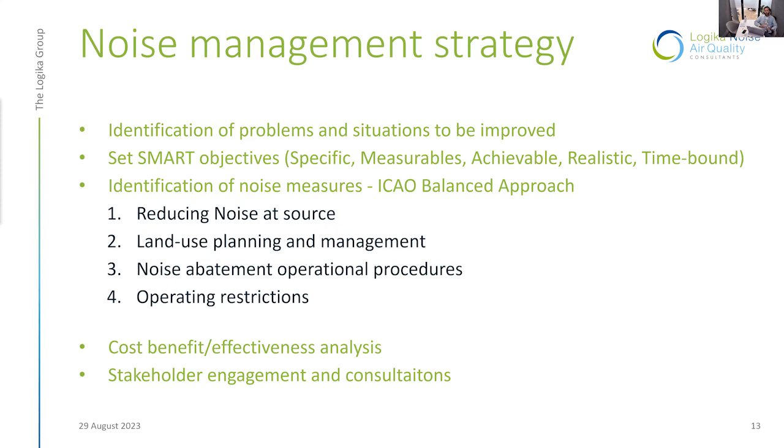And within the aviation industry, these are identified through the so-called ICAO balanced approach that tends to find the possible mitigation options by reducing the noise at source, through land use planning and management, through noise abatement operational procedures, and as a last resort, if none of these three pillars of the balanced approach can identify a solution to achieve these objectives, operating restrictions that tend to limit the operations of the airport.